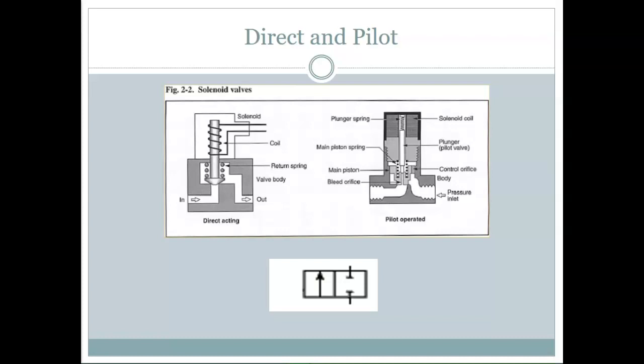We do have a range of pressures because when you're working with hydraulics, you can end up with pressure differentials moving back and forth in the system. So you have to account for that at times. But if it gets over that 70 psi limit, and yes, I'm being generous with that limit, you might have a problem with your seals once it does.